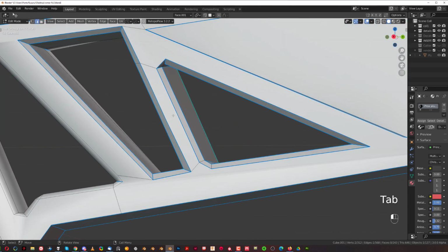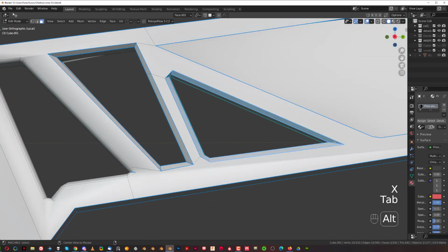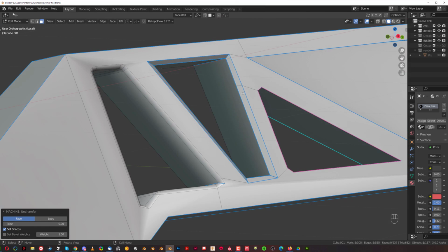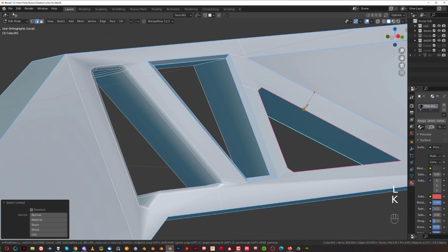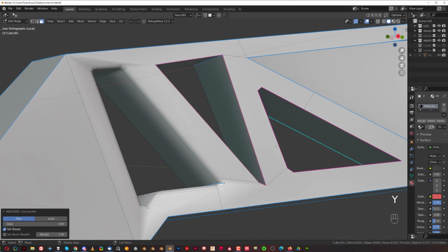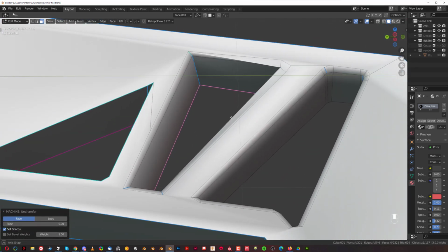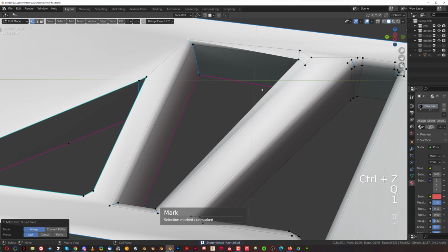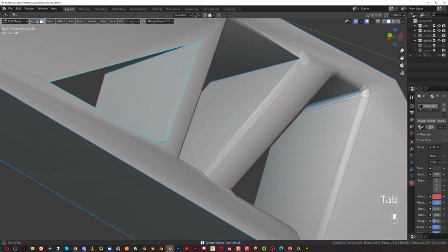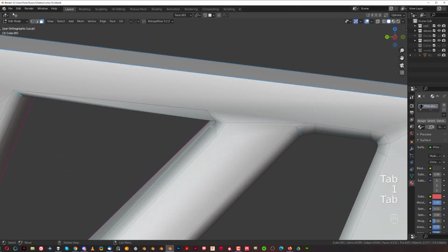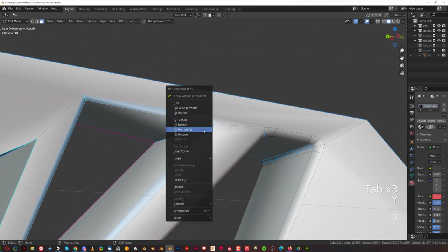And then the other side, we're gonna have to remove this edge because again, hang on, and unchamfer, boom, sorted. Now here, we're gonna have to remove this one and this one. This one will not get removed because this cut needs to be connected to something. So let's do this one, and then we can select this one and unchamfer. Go to the other side, and again, we're gonna have to do this. Combine it to the top and then select this bit here, which doesn't want to get selected for some reason. I'm gonna combine these and then we should be fine, and unchamfer.